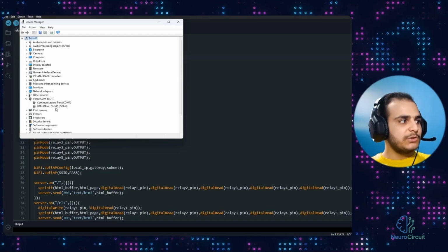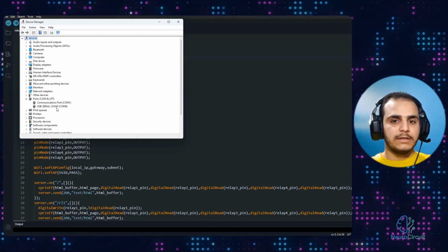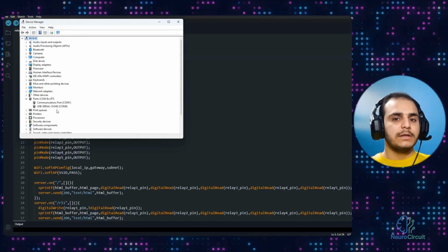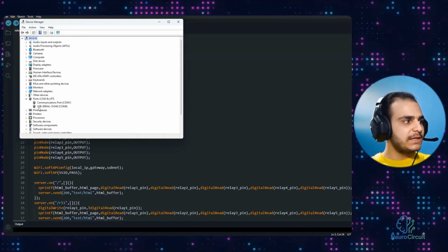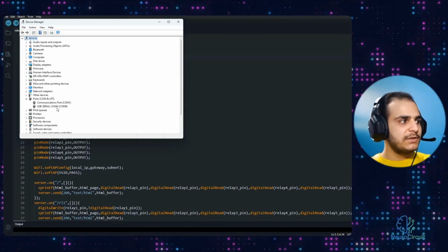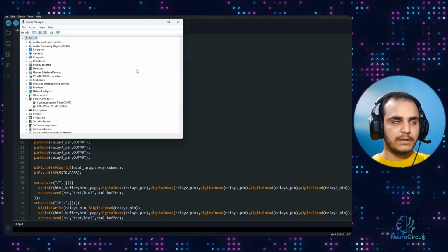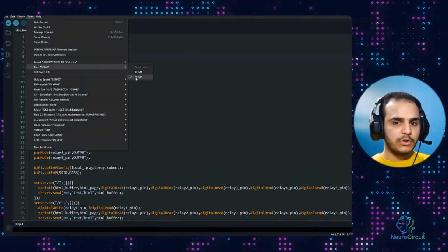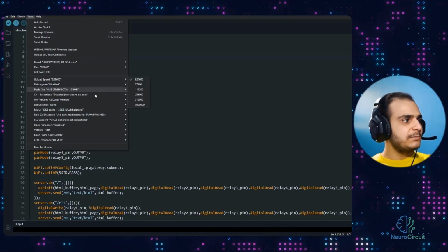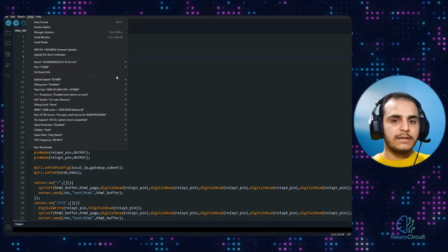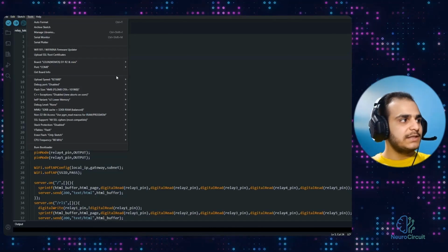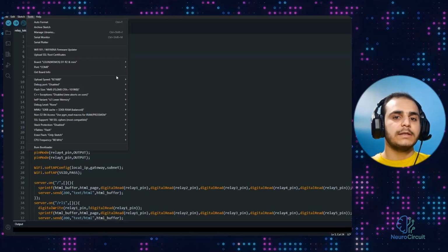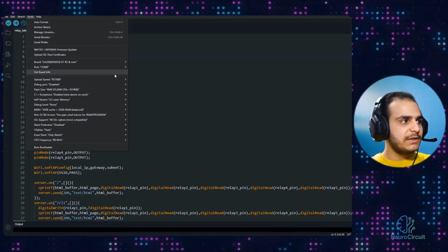Right now, the board I'm using is the Wemos D1 Mini. The serial chip on it is CH340, which is the same cheap IC model. And here it shows me that my USB serial CH340 is now on COM 8, so that means the board is connected. Right now, it's connected to COM 8, which is also selected here. After that, we have some other settings, but they're generally not necessary. You don't need to change anything here. If yours is set to something else, it's better to change it to these settings.